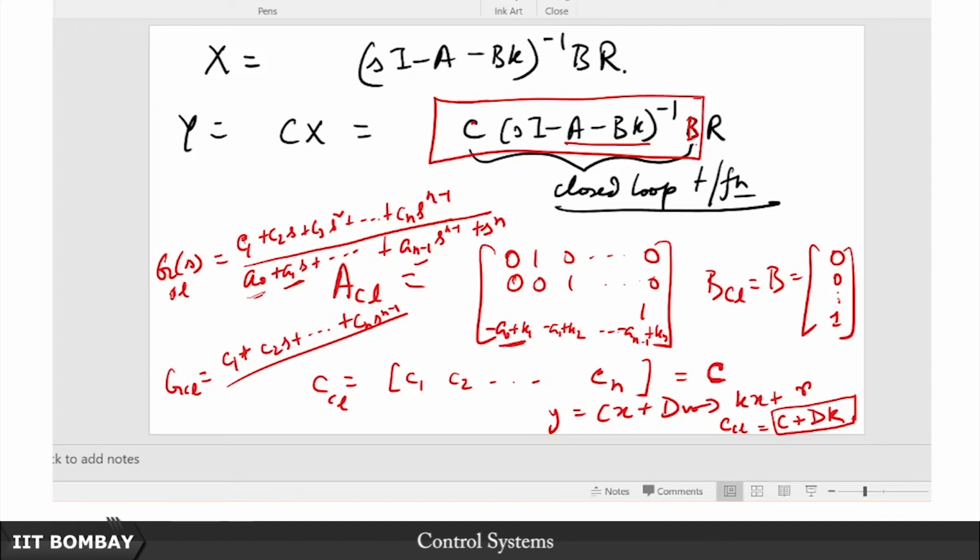So you will see that using this technique called periodic control, you manage to trick the system into behaving as if the discrete time system's zero is still inside the unit circle, although the corresponding continuous time system's zero is on the right half plane. But unfortunately those are not really linear time invariant control strategies, so those will not come within the purview of whatever we have covered here. So that I hope summarizes the joint controller and observer design technique.